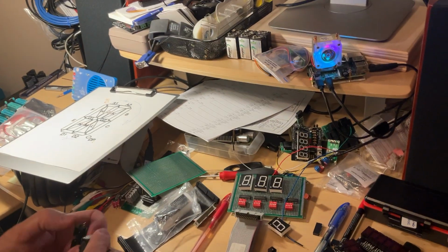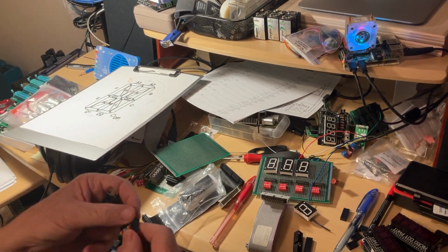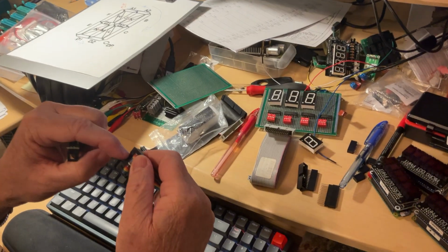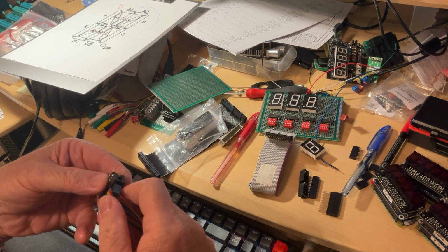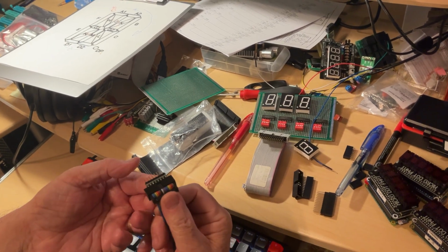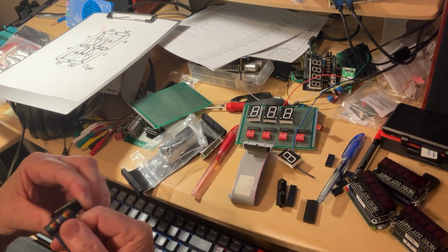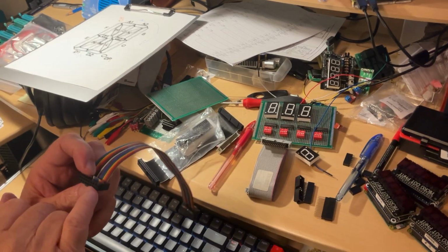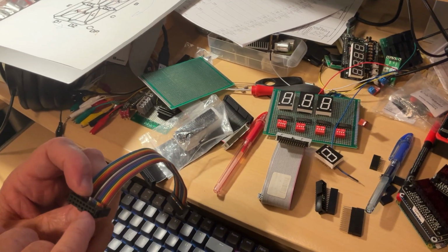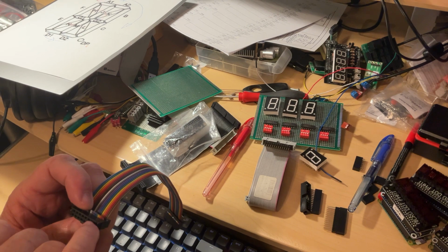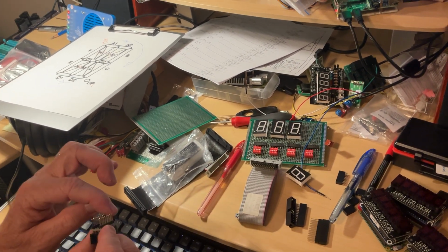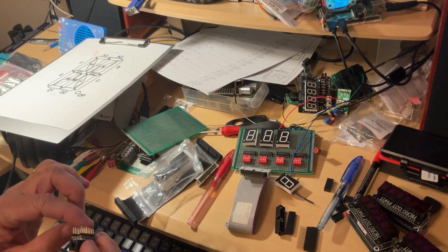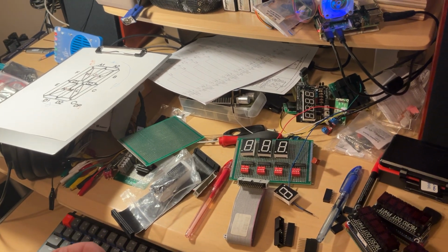And that connector here, if you take a look around it, where I put my finger, it has a notch, and the notch has to be aligned with the opening here. Okay, and that's how it's going to enter. But when you remove the cable, the pitch is exactly 0.1 inches or 2.5 millimeter, exactly like here. And on the other side, you have 0.3 inches, so you can plug it on a breadboard.